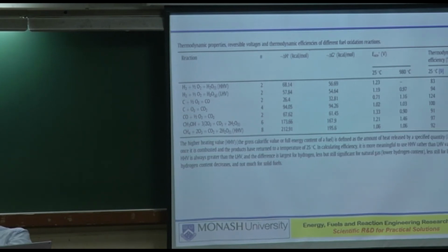When your input is in the denominator, if you give the input on the basis of lower heating value, then it is a smaller number. Just to give you an example, for our brown coal, the higher heating value is about 26 megajoules per kilogram, but when you account for the 60% water in it, its lower heating value is about 8 megajoules per kilogram.